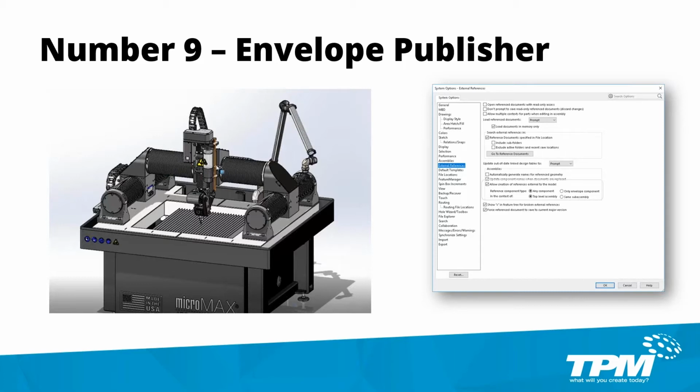When you're working on really complex assemblies with multiple subsystems, it can be challenging when you are trying to reference between subassemblies or when you're referencing a subassembly from the top level down. So the envelope publisher actually allows you to do that while maintaining external references, and it won't break your assembly. It allows you to work with other users on an assembly without creating a bunch of external references that prohibit you from doing so.